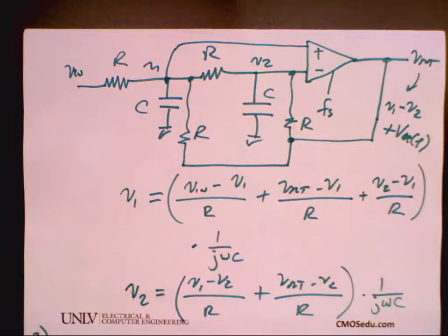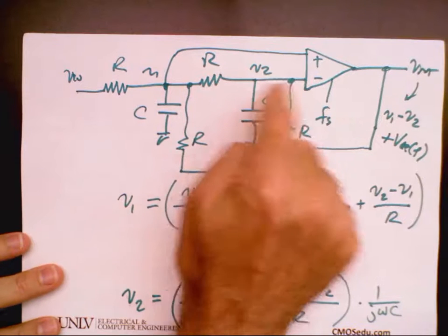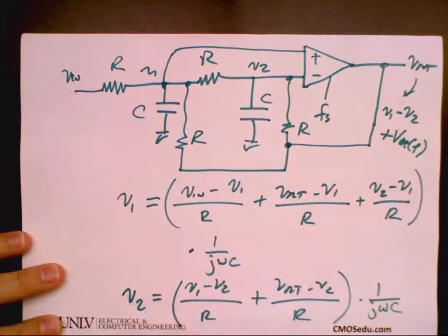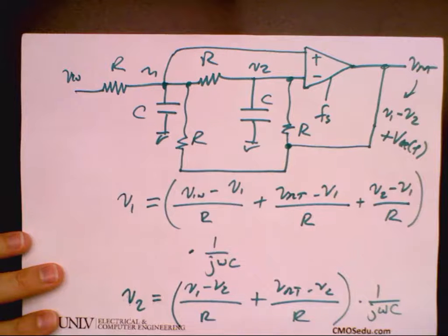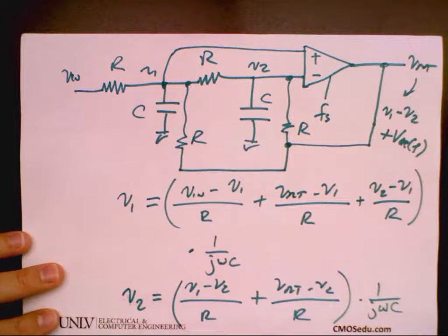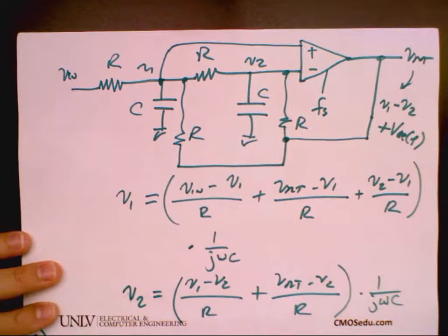Well, I could put like a diff amp or something, right? I can't do summing because I need the difference. So I could use a diff amp here, which would increase my forward gain, which is good. And then the output of the diff amp would go into the ADC. And I'd amplify the difference.